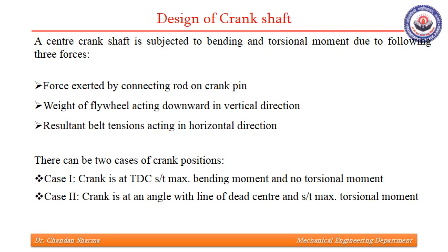We all know that a center crankshaft is subjected to bending and torsion moment due to three forces. First is force that is exerted by connecting rod on the crank pin. Second is weight of flywheel acting downwards in vertical direction. And third is resultant belt tensions acting in horizontal direction.